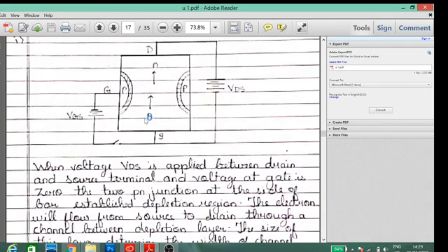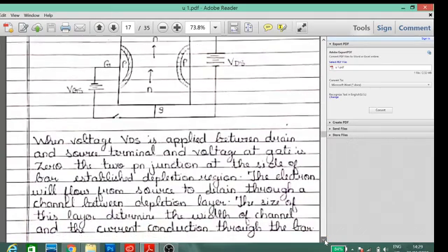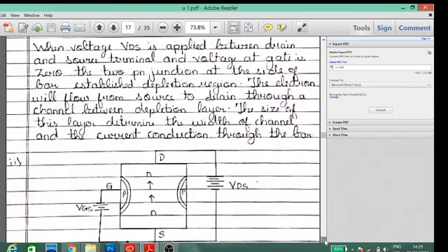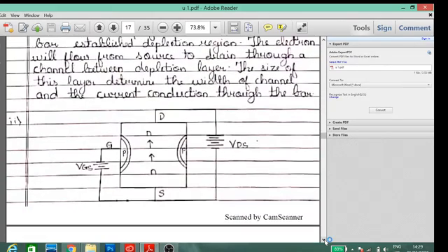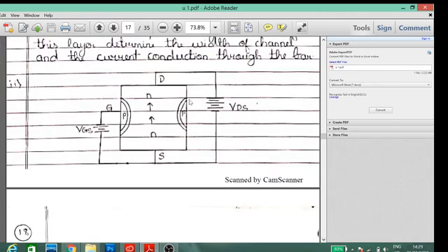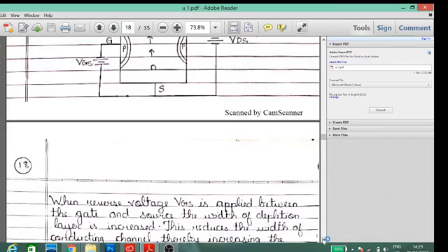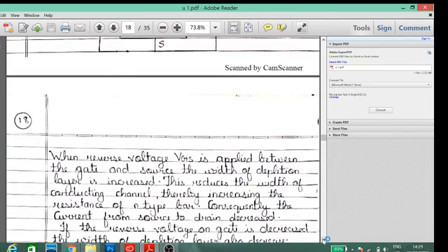The number of carriers that cross the channel is limited by the depletion region between these PN junction diodes. Second, if we apply a small gate voltage that is negative, the depletion region increases inside the channel and we will get a lower ID at the peak.